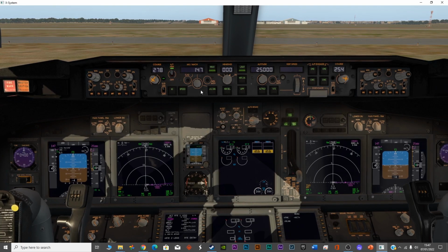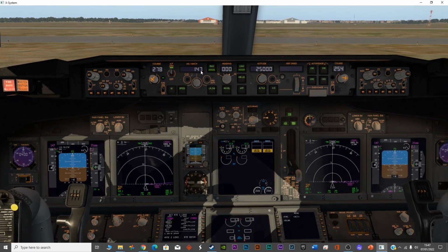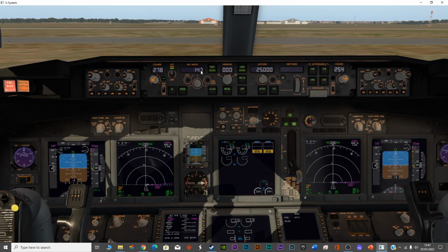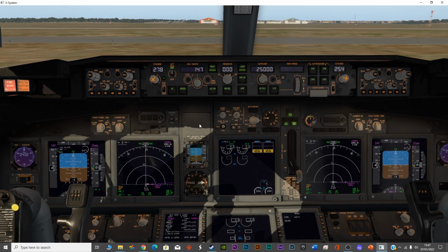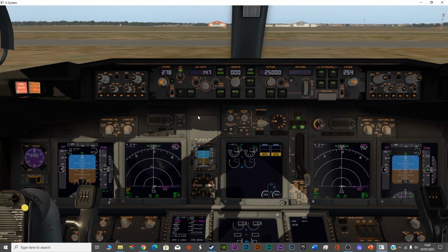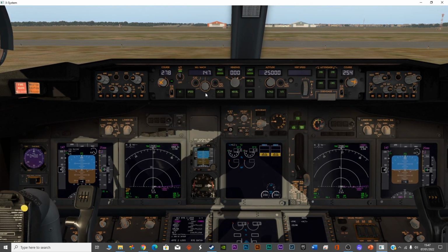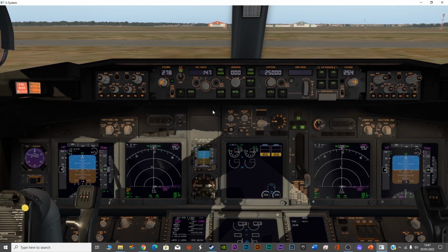So after the takeoff, you have to be at the speed of 147 if the engines fail, because V1 is the point on the runway up to which you can abort the takeoff and still go back. But after V1, you then have to take off the plane, which is VR, rotate, and V2 is the speed at which the plane can fly with even a single engine if there's any kind of failure or fire. So the main objective of the pilots is basically to achieve 147 knots, so that they're in a safe position, and in case of failure they can always go around or come back for the landing.